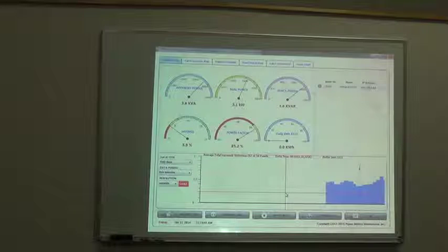And you want to gradually go to a solution. You don't want to apply everything in one shot. Well, if one of those frequencies happens to be in resonance with the rest of the system, then you want to avoid that. And that's what we mean by mitigation. Okay? So that's basically how we deal with the harmonics.